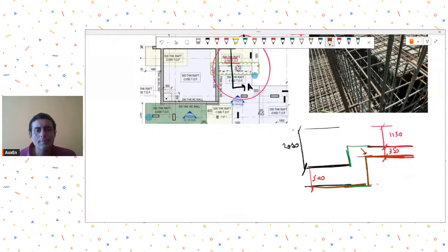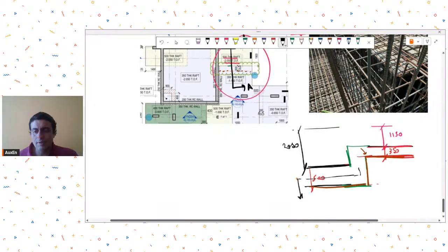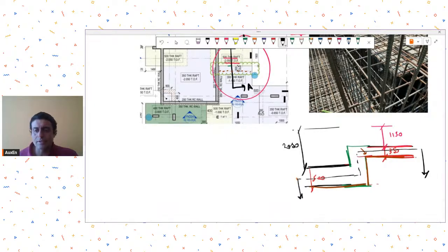Wait a minute, I'm just thinking. Actually, they should not have drawn it like this. Because we generally cut this section looking downwards, there is a small mistake in this drawing. What they should have done is this orange line should have been made dotted, which would have represented this, and this brown line should have been made solid, which would have represented this line.